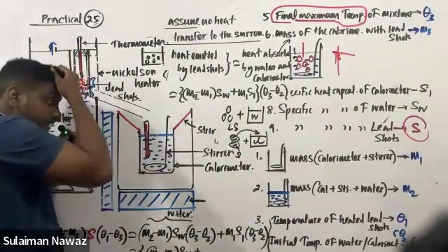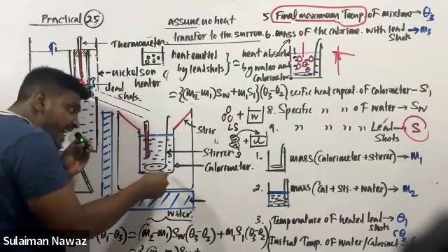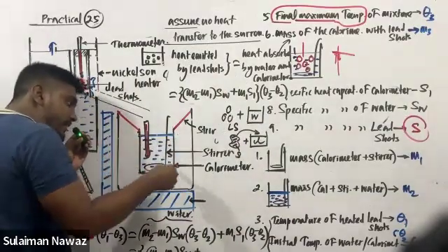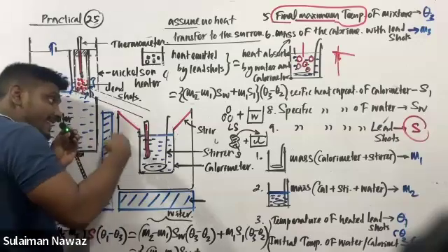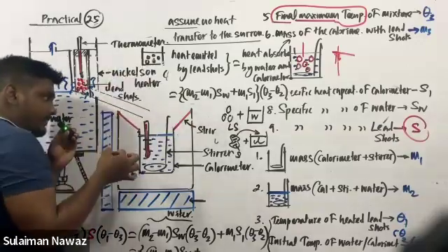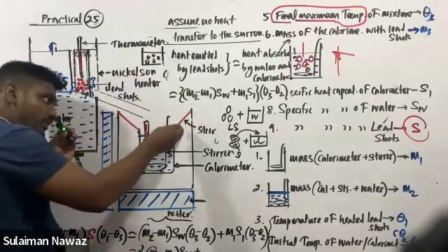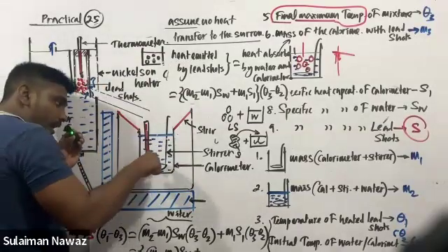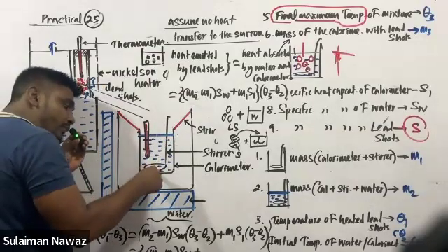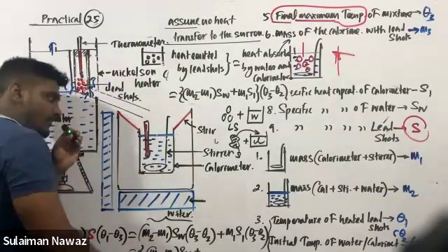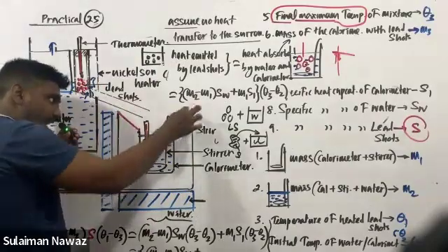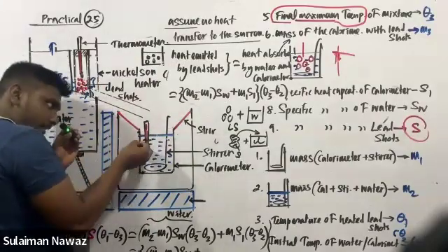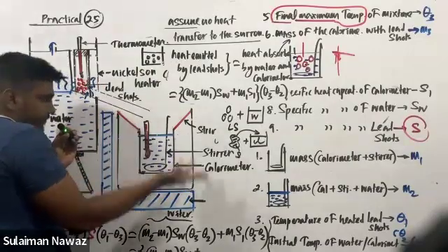Heat can transfer from the calorimeter to the solid surface. So to avoid that, we hang this heated calorimeter in another container using strings. What would happen if you don't use the strings and just keep the container on it? Heat transfer happens from the calorimeter to the container through conduction. But if you hang it using strings like this, the heat transfer through conduction is minimum.